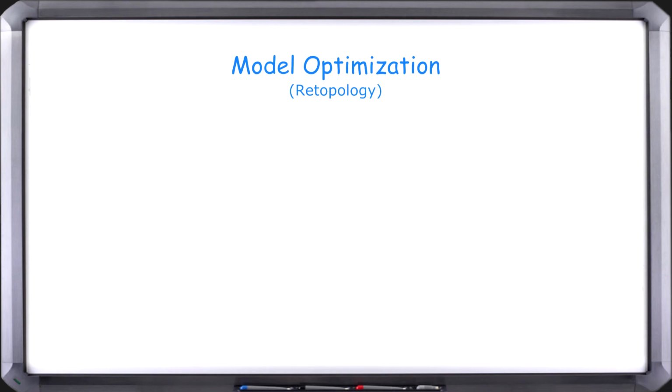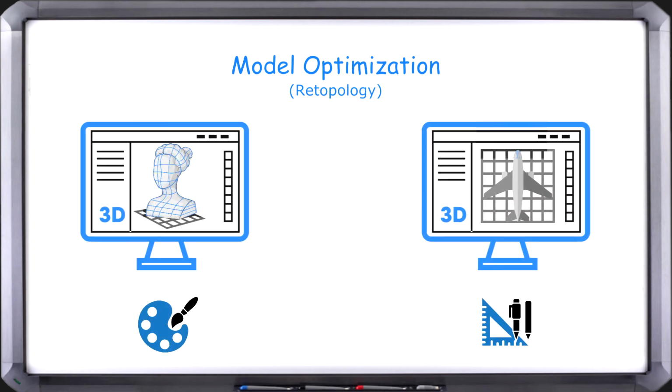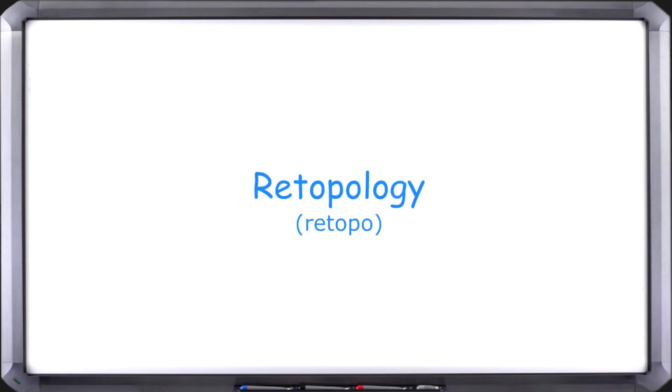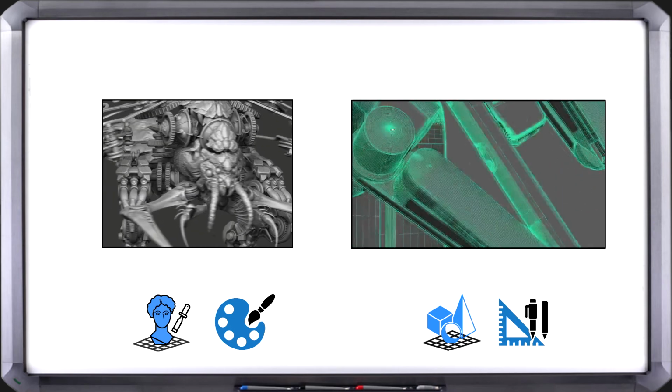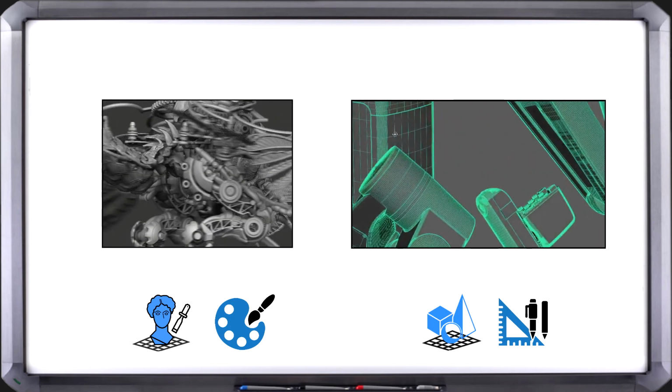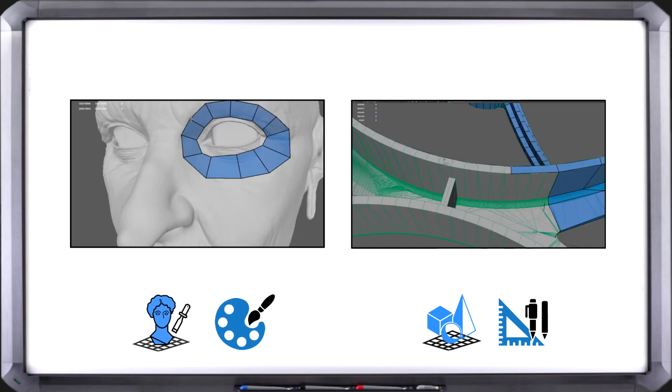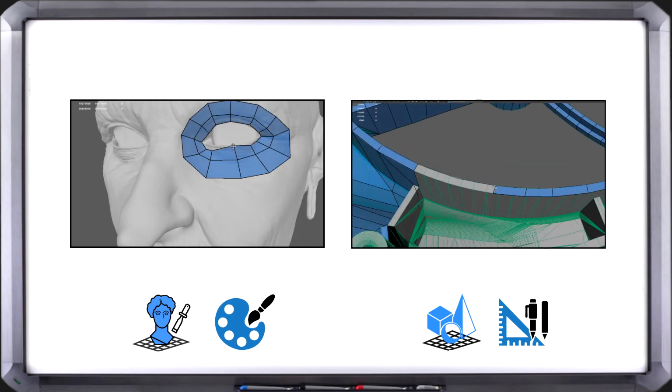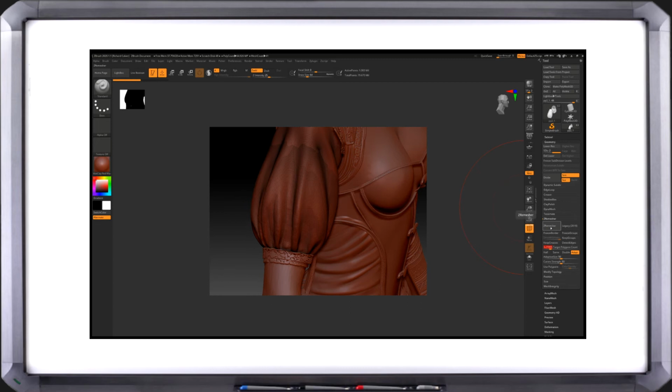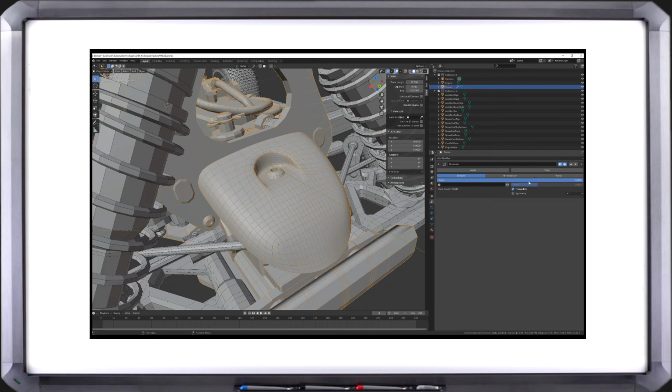In either of these cases, creative or reproduction, the next phase is a process of optimization which begins with what is termed retopology. In other words, replacing the higher resolution source CAD file or sculpt with a lower resolution mesh. This is usually done by hand or using specific remeshing algorithms designed to create clean meshes. It has been our experience that decimation methods are not efficient and more often than not break the mesh or make them inadequate for later phases of the pipeline.